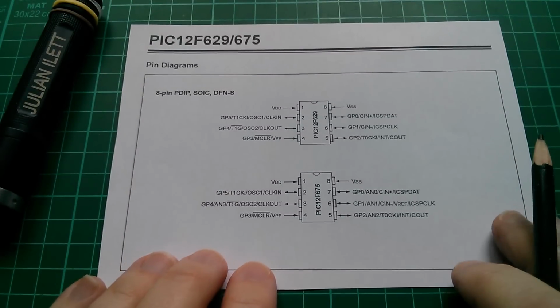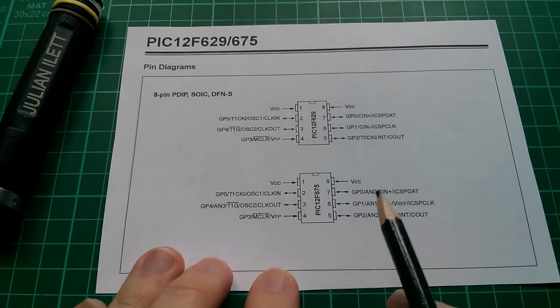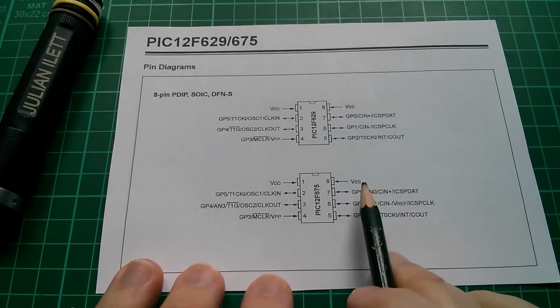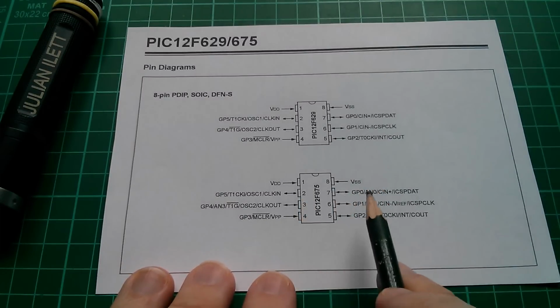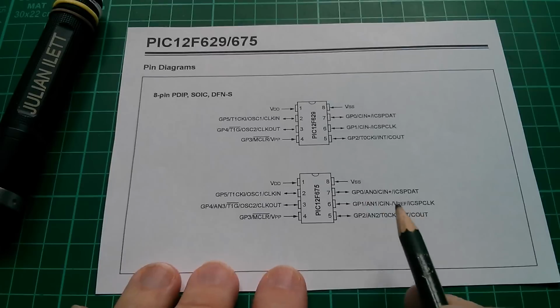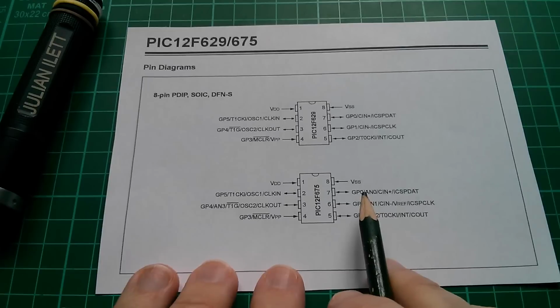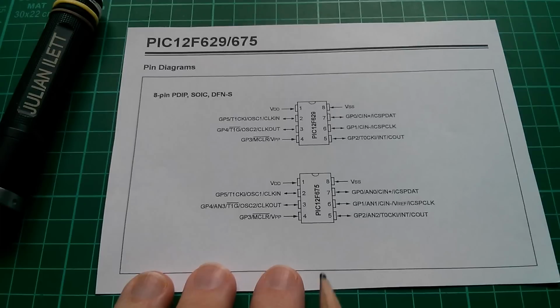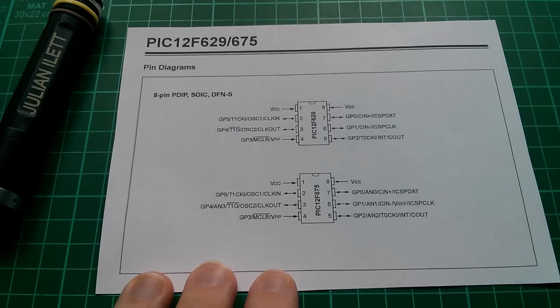Now, I don't know this for sure, but it's my guess that all microcontrollers will set their I/O pins, and this particular microcontroller has 6 I/O pins, to inputs when they first boot up. It would be very dangerous to set the I/O pins to outputs, because if you have something connected here like a machine gun, and the output comes on high or low, or whichever way you've wired your logic, you could set that machine gun running when the chip first boots up. You don't really want that. So microcontrollers boot up with their I/O pins set to inputs, and that's no good for flashing our LED.